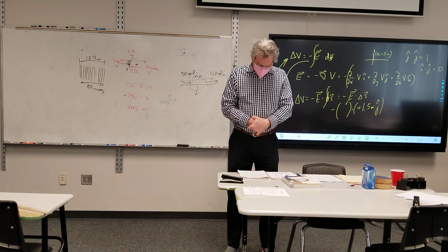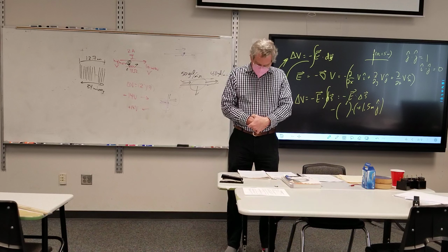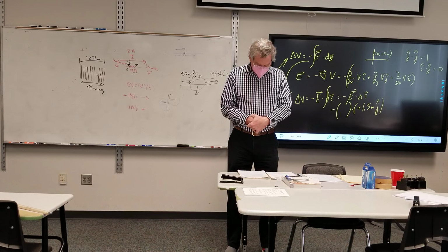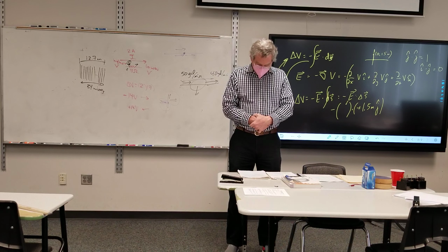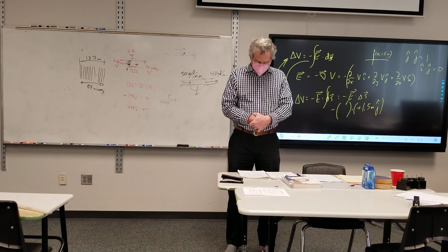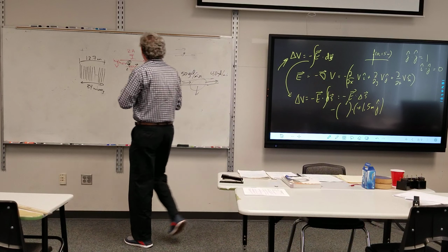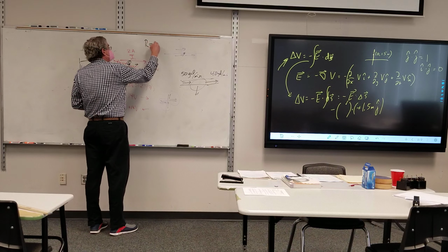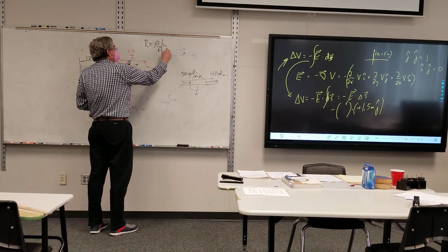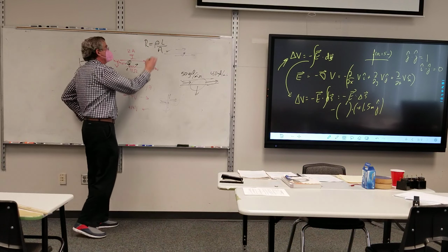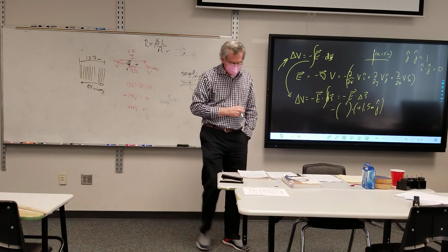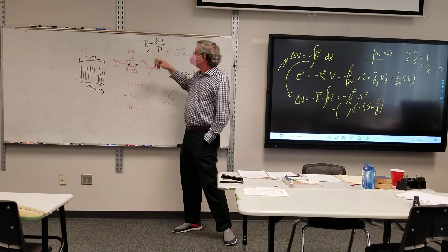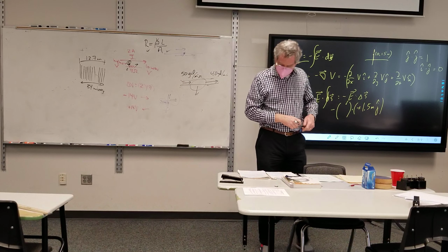And then the length of the wire. It's copper, so you can look up the resistivity of copper. I know that resistance is rho L over A. You know A at this point. It's copper, so you can look that up. I give you R, don't I? Yeah, you do. I give you R. Solve for L.